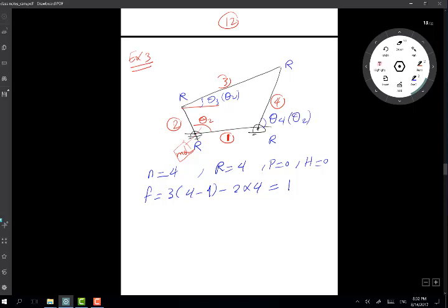In fact, any other x and y values can be a function of theta 2, my single degree of freedom. I'm just repeating the definition of single degree of freedom here: the number of parameters required to calculate the position of any link or point in the linkage, or the number of motors required to run the linkage.